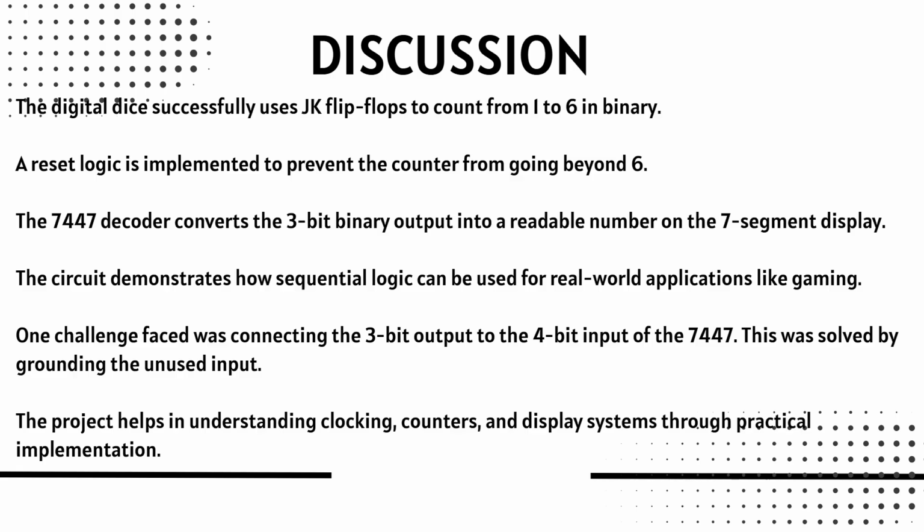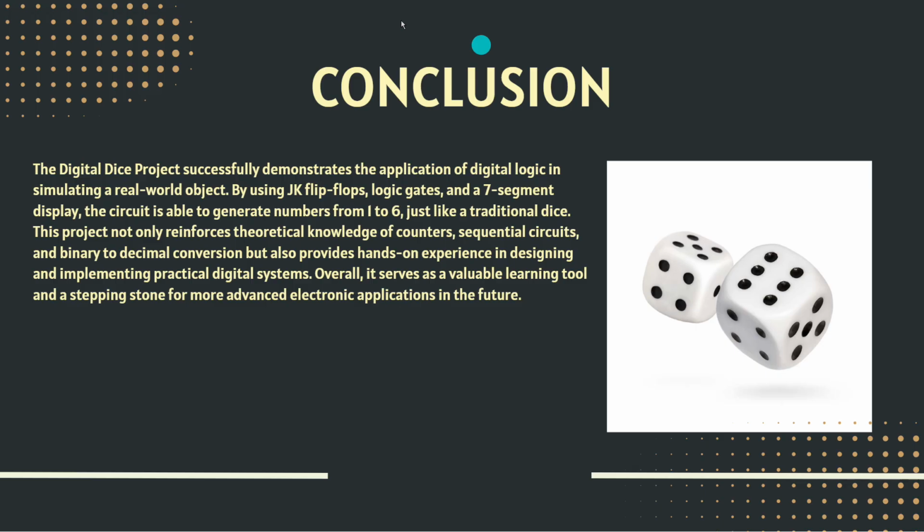One challenging phase was connecting the 3-bit output to a 4-bit input of the 7447. This was solved by grounding the unused input. The project helped in understanding clocking, counters, and display system through a practical implementation.